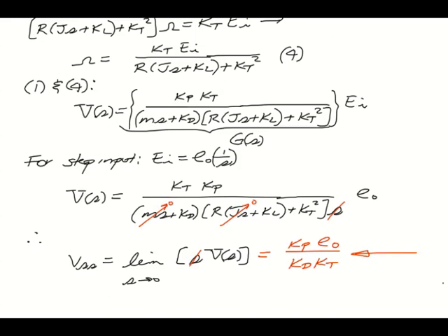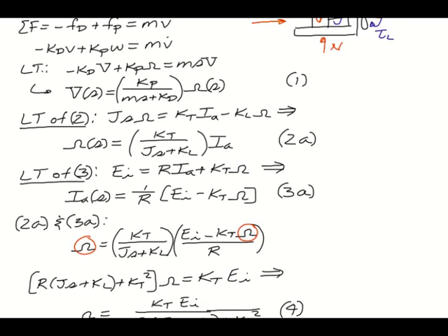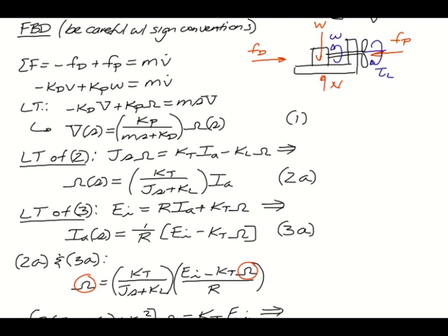So let's go back over what we did. Equations 2 and 3, that's just a repeat of our motor equations, and I think the key thing for us here is to be sure that we get the right sign convention on tau_L. When we derive the motor equation, we have the sign convention tau opposite to the rotation rate, and so that allowed us to directly put in K_L omega wherever tau_L appeared.